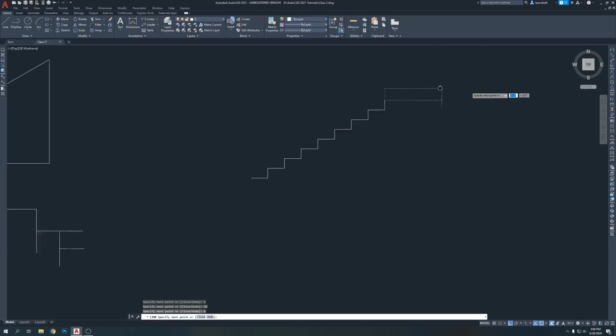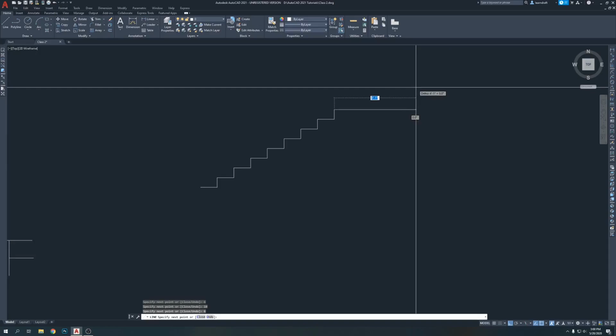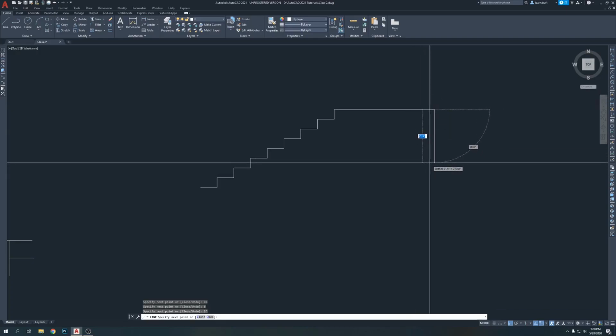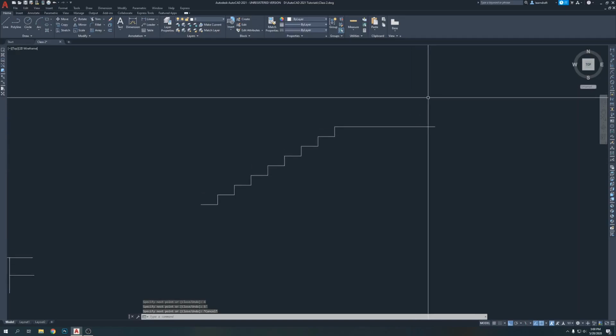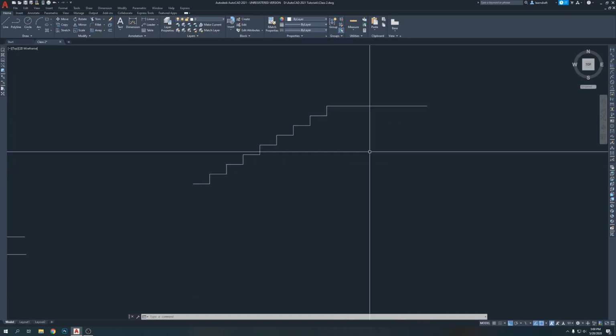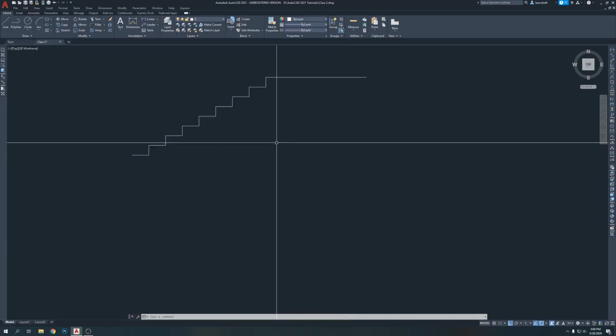Then let's say we don't know how many we made, but let's say that's good. So make it 5 feet. This time I'm going to make it 5 feet from here instead of 60. Enter. Now I'm going to bring it down, or you just press escape on the keyboard. That's your stair. Now we try the extend tool again, but let's try a different way.